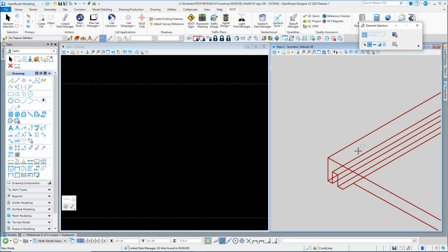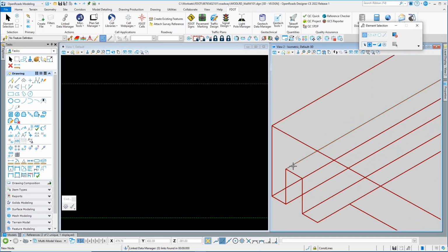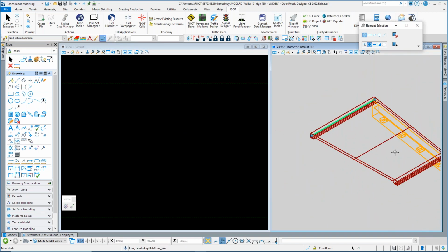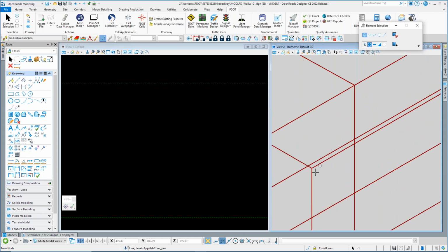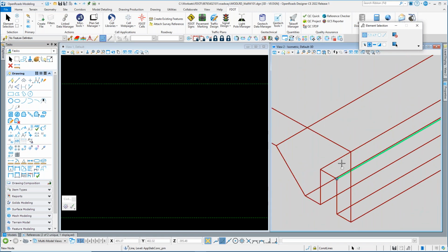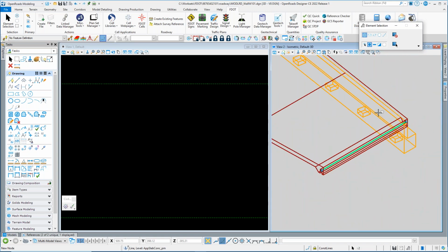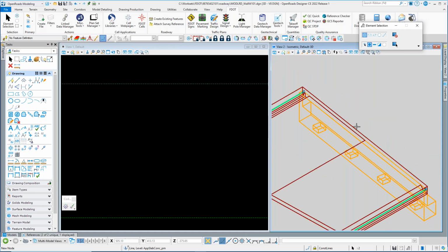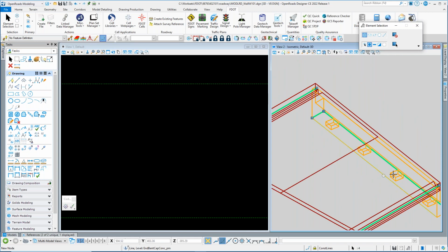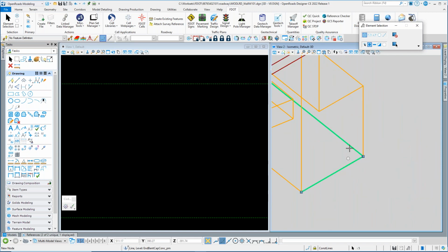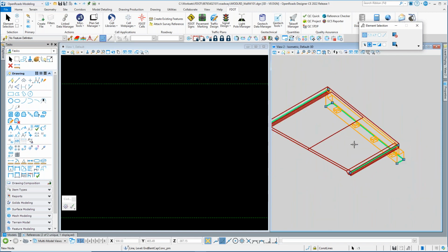So we're going to start choosing the 5 edges that we're going to use to skin out, or place the facade around this with our templates. This is going to be the top outside edge of the notch in the approach slab. We're also going to choose the side, the front, and the other side of the end bent back wall.